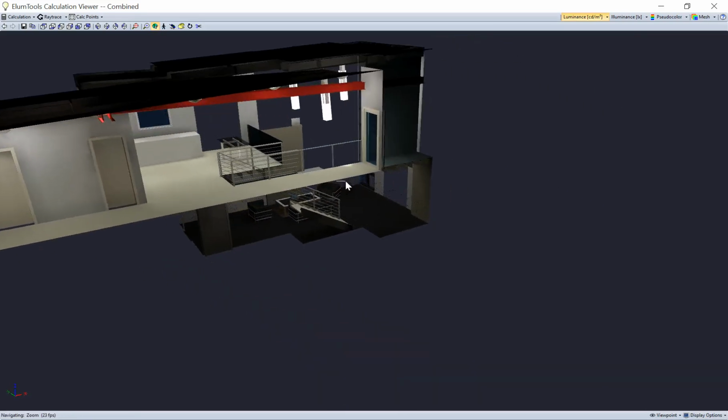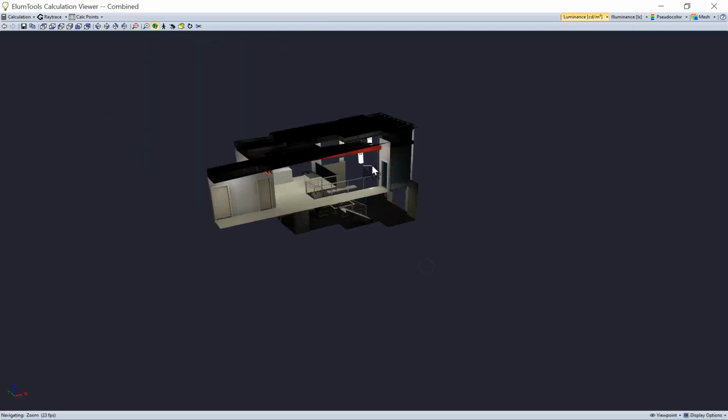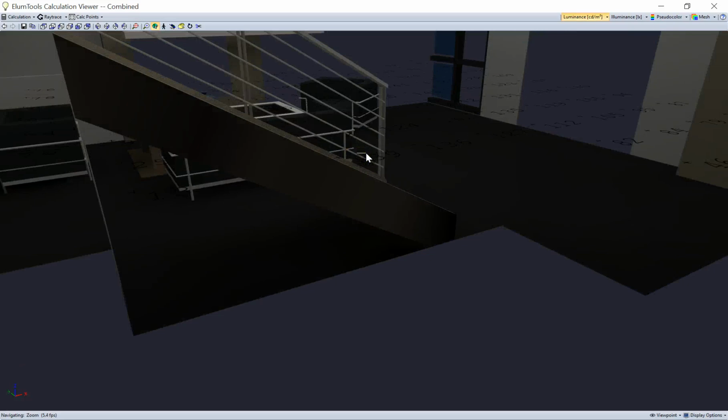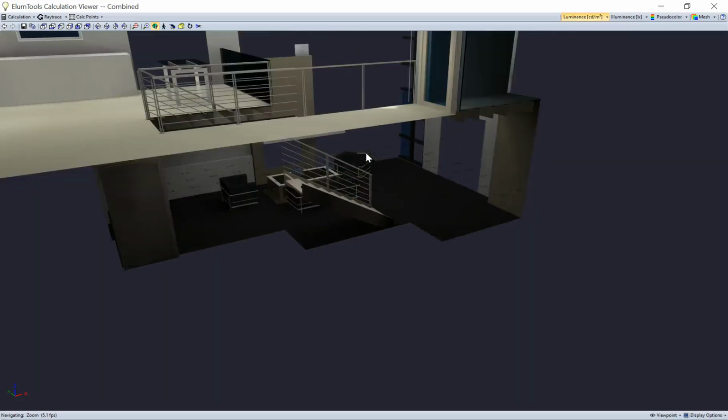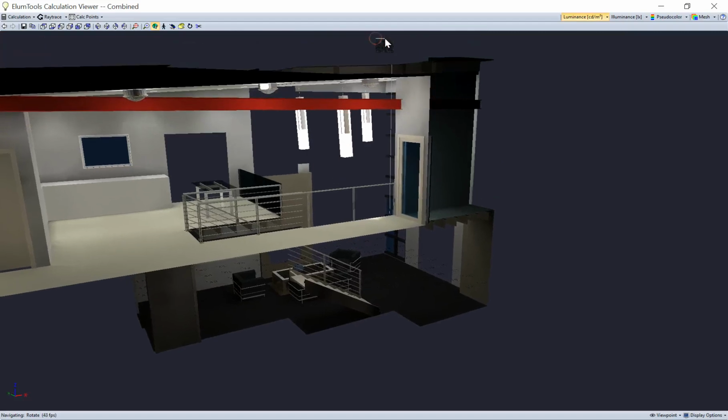Turn this around. The way one of these fixtures is built, it does create a fairly odd, a little zoomed in display, because of the way the IES file is made, there's a light source that becomes visible once you actually render it. So while the light fixtures don't look like this with this glowing box in them, that's just how the IES file works. So the first thing you see is an accurate rendering of where the light's going to go.